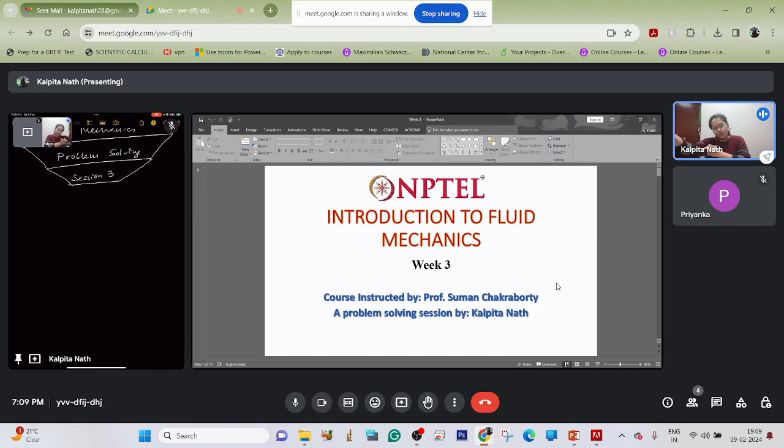What he taught in class was that there is a viscometer where some fluid is present in between two circular cross sections, where the inner one we can move, and the outer one is static, like this. I won't go through the whole derivation, but I'll just give a brief idea of what Sir taught, so that we can understand what we are going to do in the class. The inner one is moving with angular velocity, and there is a fluid having viscosity mu in between.